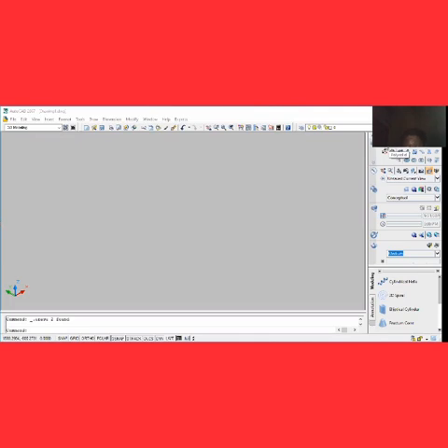Using the polysolid command, you left click on it and then come to your drawing area. Now your command window says specify start point or adjust the height, the width, or justify the command. So now we can decide to click anywhere on the drawing area. After clicking anywhere on the drawing area, we can move anywhere we want to position the polysolid. So this is how it is.